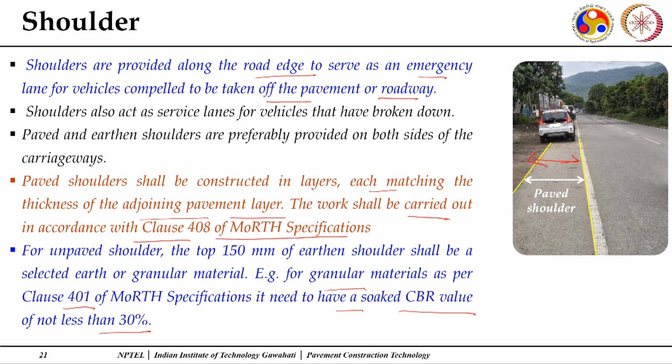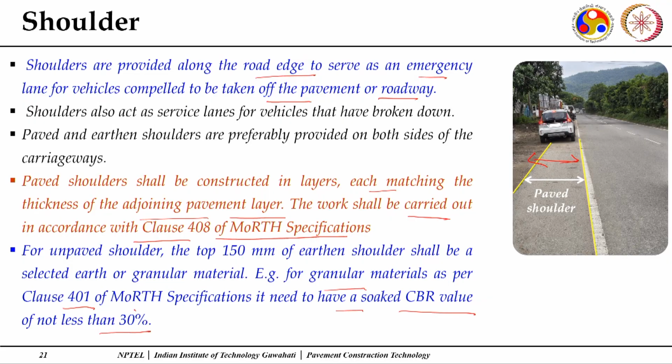This again, when we discuss the subgrade course, we will discuss the CBR requirements, and for granular courses also. CBR, California bearing ratio, is a penetration test which gives you an idea about the strength of a soil or any granular material, and the strength of that material should be at least this much value. So when I discuss the California bearing ratio in the shoulder part, I will again discuss the CBR value.